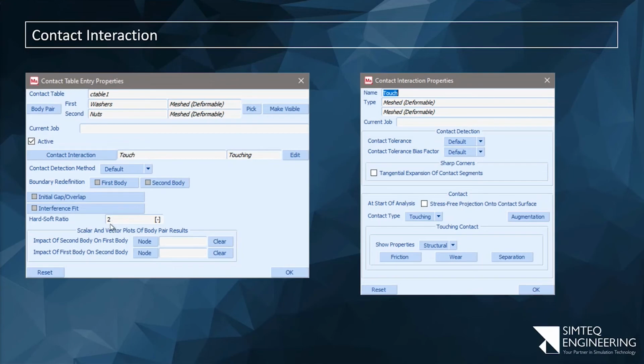And this is a setting that simply says, well, if the one mesh is finer than the other, but we also have, let's say, the rubber is the coarse mesh. Ideally I want the steel then to touch the rubber, but the rubber has got lower stiffness. So at a ratio of about 2:1 in terms of elastic modulus, it should then rather make contact from the rubber to the steel. To be honest, I don't use the automatic setting, and even in that case, it's better to rather remesh the rubber so that it matches both. So the rubber is the finer mesh and the lower stiffness, which makes sense.